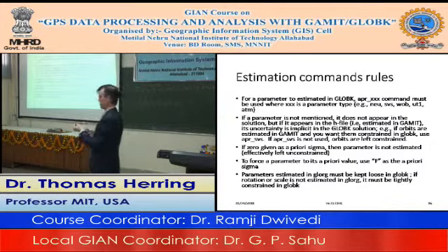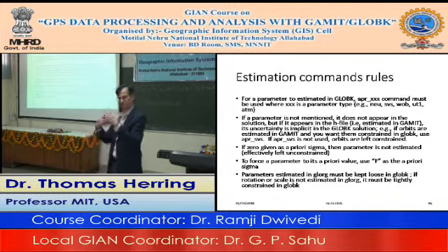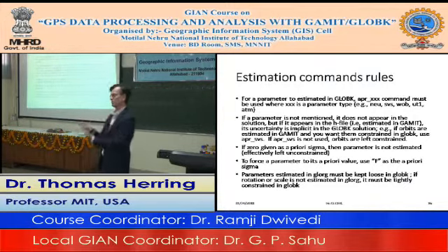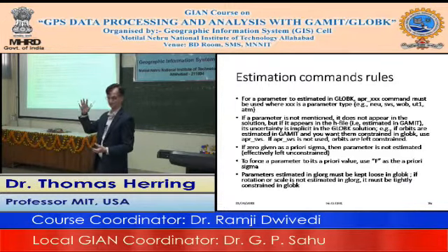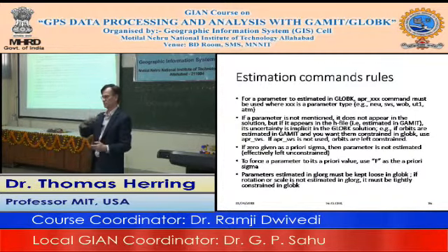And again, we could spend a lot of time talking about scale. You'll see, when you look at the IGS literature and what people do, and a lot of papers, people just sort of come in with this natural thing from, I think, conventional geodesy of estimating scale all the time. But what scale is in GPS is the average height of your system. Because the Earth's pretty circular, if you take a spherical body and scale it, all it does is push everybody out in height. And so when you estimate scale, what you tend to be absorbing is any average height difference.